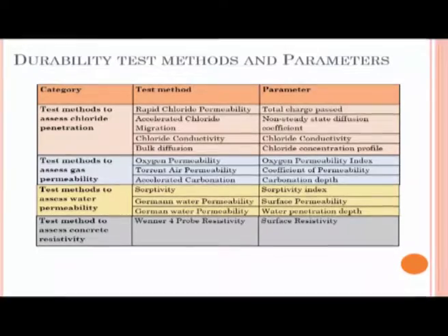You will be addressing more the issues of chloride penetration, you will be addressing the issue of water penetration, okay. So depending upon the kind of environment, you will have to choose the type of test methods that you need to perform on your concrete specimens and assess the durability appropriately. So you can't do one test and expect it to solve all problems. Depending upon the type of environment, you need to tailor make or choose the appropriate test that addresses your particular problem, okay.